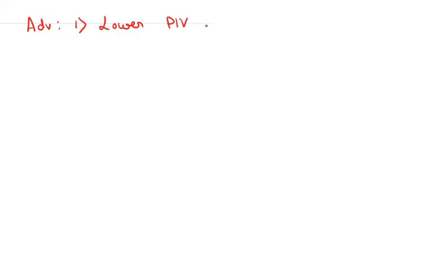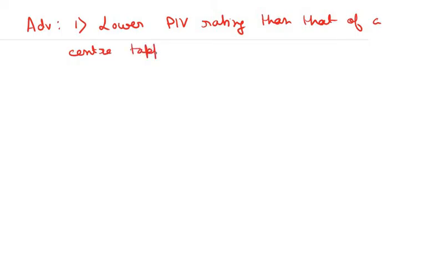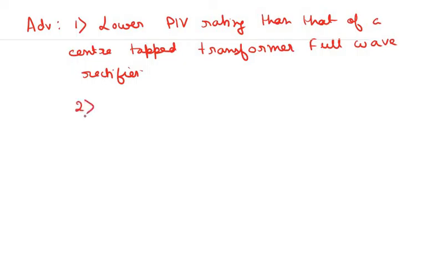Lower PIV rating than that of a center tapped transformer full wave rectifier. And the second point is that there are fewer turns in the secondary coil.